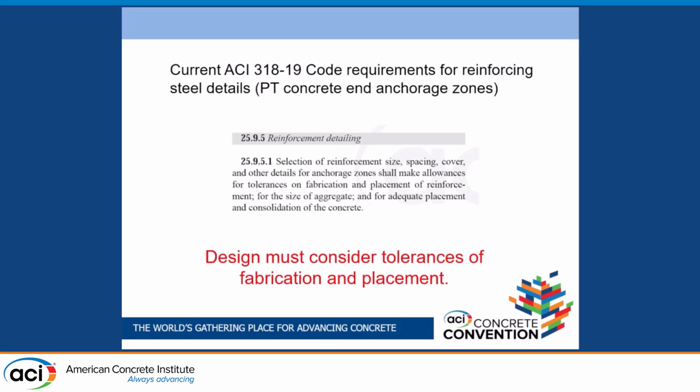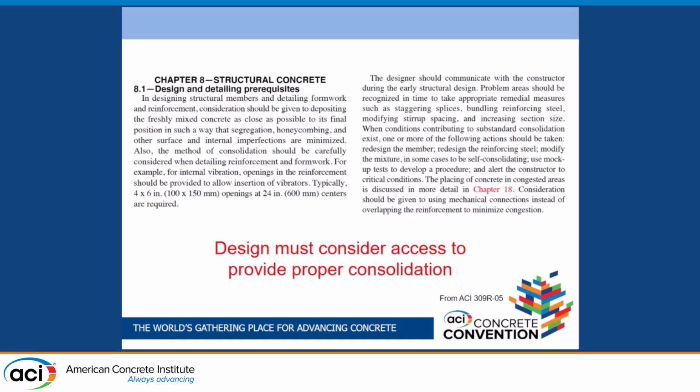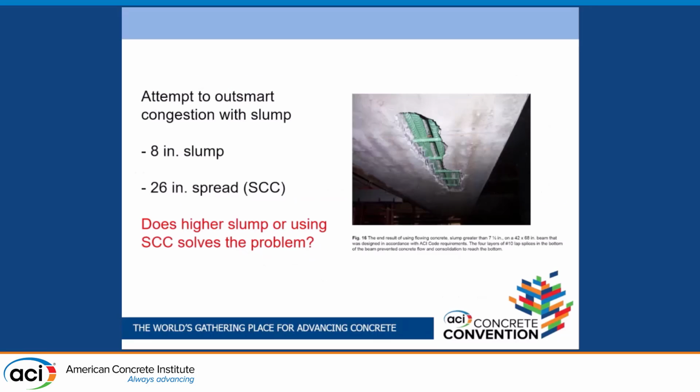Extremely important too. If you don't consider the way it's going to be built and leave a space for the material to go through the rebar, you can create some issues there. Design must consider access, because if you're going to build it, you need to provide access to get to the point where you need to place the concrete, right? Otherwise, what are you doing? If concrete cannot flow there, then you don't create the encapsulation you assumed in design.